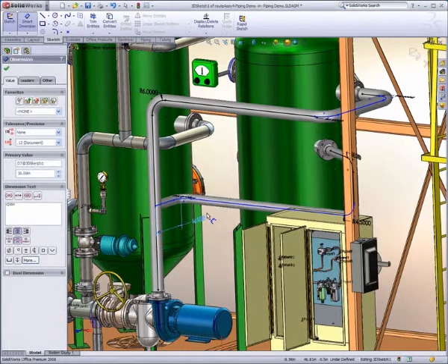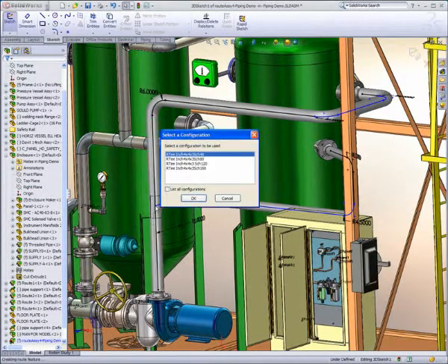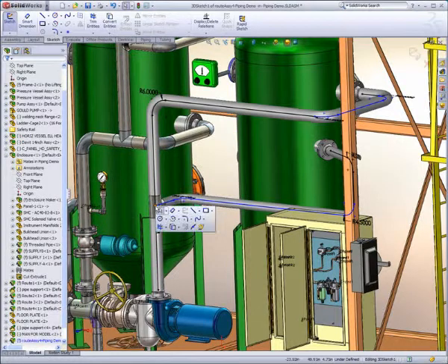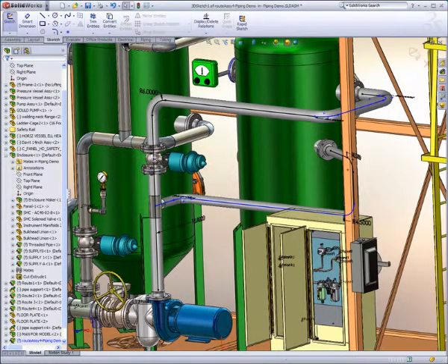Pipe fittings, such as a reducing T, can be easily applied by dragging them from the library. SOLIDWORKS automatically sizes the connection based on the piping information. Other components, such as a valve assembly, can also be included in our system. All I need to do is specify its location and drag out the style valve I desire.